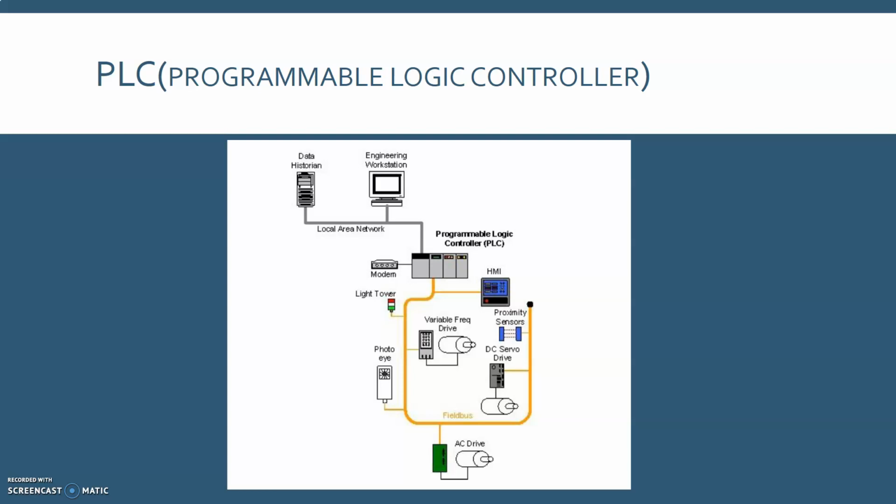PLCs have a user programmable memory for storing instructions for the purpose of implementing specific functions such as I/O control, that is input output control, logic, timing, counting, three mode proportional integral derivative, that is PID control, communication, arithmetic, and data and file processing.